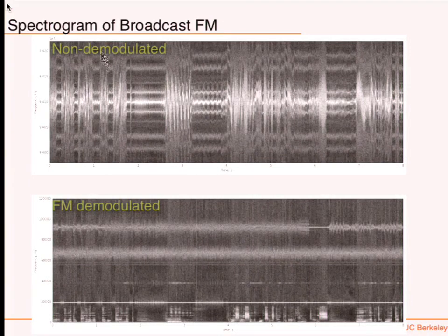This is complex values, right? The SDR gives you complex values because it represents only one side of the spectrum. Remember, we talked about why it does. It represents frequencies from 9.4 megahertz to 9.42 megahertz, so this has to be complex. It's just one side of the spectrum.